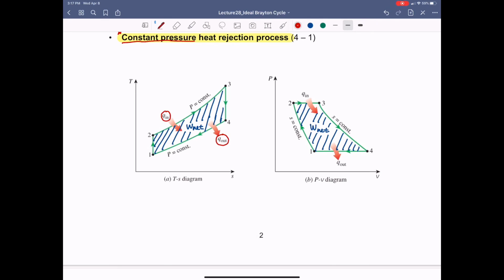And for the Diesel cycle, we had two key design parameters, which are compression ratio and the cutoff ratio. But in both these engines, the compression ratio is very important because the piston moves up and down to compress the air in terms of its volume from the biggest volume to the smallest volume. So that's why the compression ratio is very important.